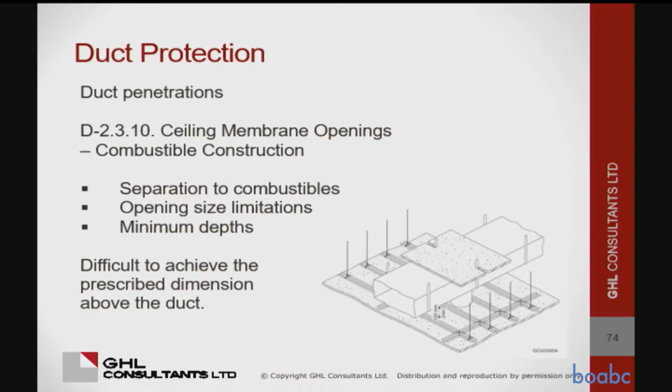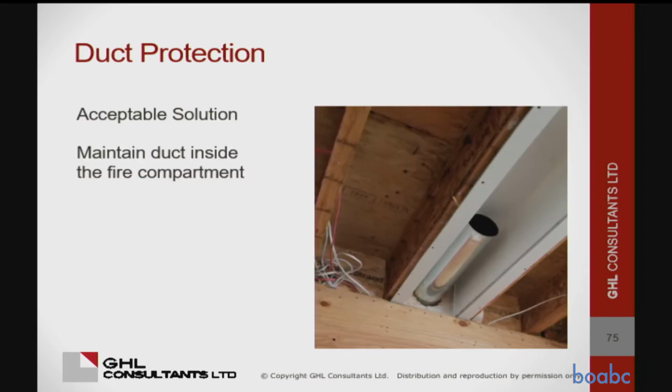That's a different conversation. Oh, this thing, it never works. It looks nice in the book, but the ceiling cavity is never deep enough to make that work somehow. So we do other things. We run the ceiling behind the duct so that the duct is inside the fire compartment.